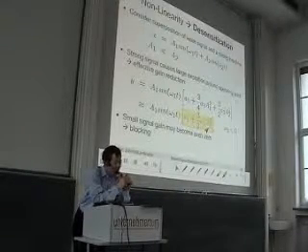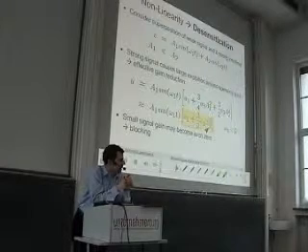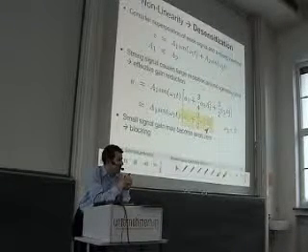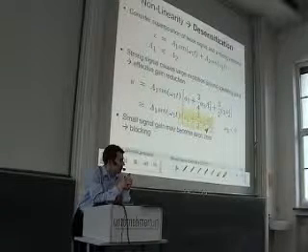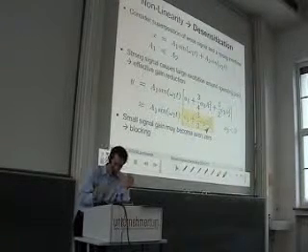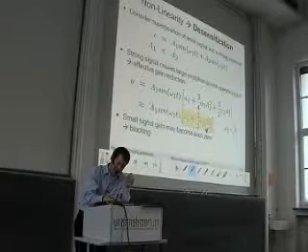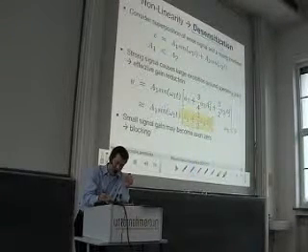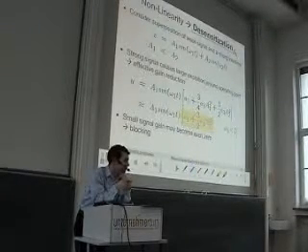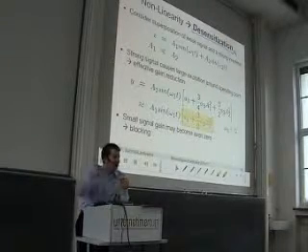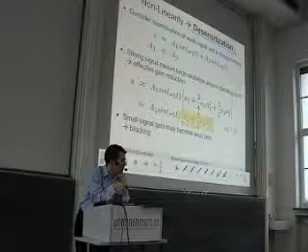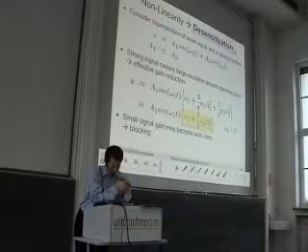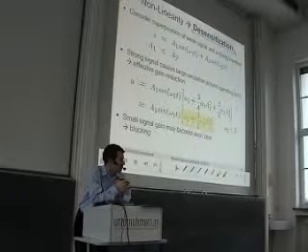And this can be even so strong that the gain of the first signal becomes zero. And this is what people call the desensitization, that we make the system insensitive for the first frequency just by having such a strong disturber nearby that the gain of the first frequency is going down.